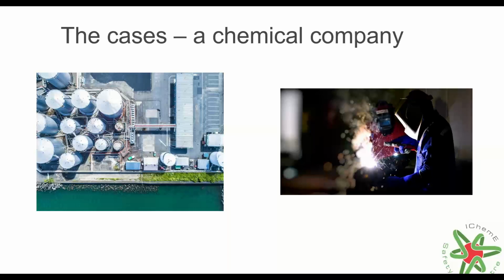So you can see there are a number of different things that fell down in that particular incident, most notably that the scope had changed, but the work hadn't been reassessed, and then the isolations hadn't been rechecked to ensure that there was no pathway to have a flammable atmosphere in the tank that was actually being worked on.